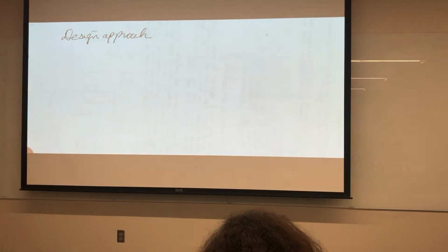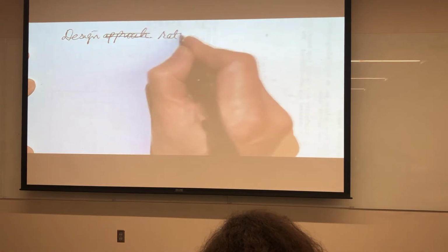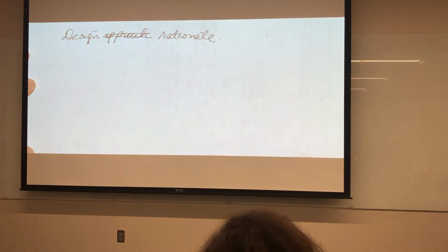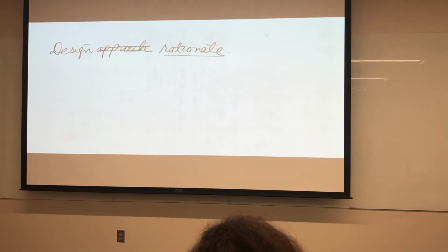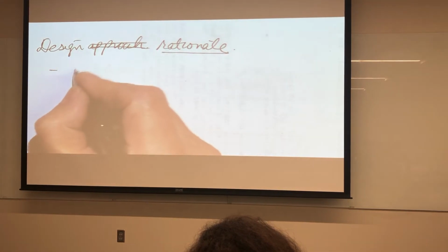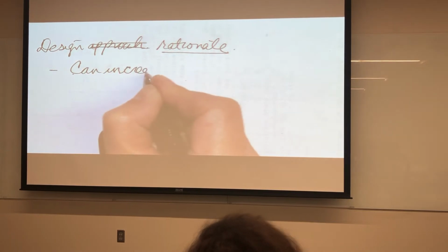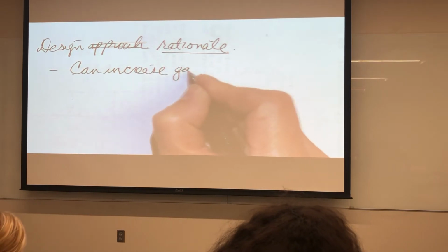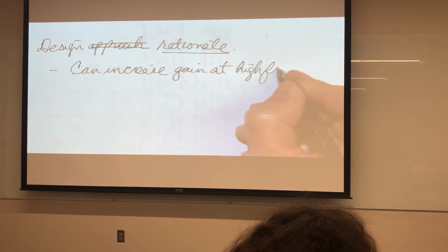Okay, the design approach. Or before I talk about the design approach, let me talk about why we would use a lead compensator. What was the design rationale? Why would we use a lead? One of the things that we see is that we can increase the gain at high frequency.